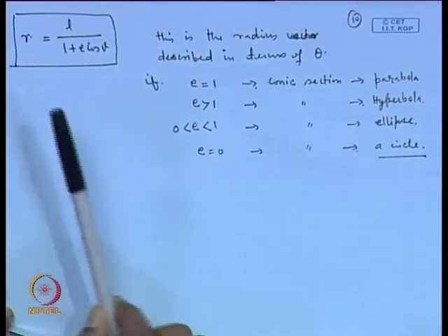So accordingly the e will be fixed. The velocity vector and the radius vector both have 3 components, a total of 6 components. Initially we know these 6 components from the onboard inertial measurement units. From there we have the 3 components of velocity and 3 components of the radius vector, and they help in determining all these parameters which are involved here.